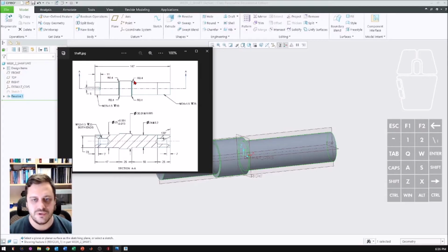The typical tool radius that you'll have on the tip of the tool, they're not perfectly to a point. They'll generally be in the order of about 0.4 millimeters. It does depend what type of tool you're using, but a rule of thumb you can use is if you put a 0.4, a machinist is going to know that that's simply going to be a tool radius. Depending on the stresses acting in a particular item, you may need to specify specific radii in corners. But in this instance, we're just looking at simply using the tool radius.